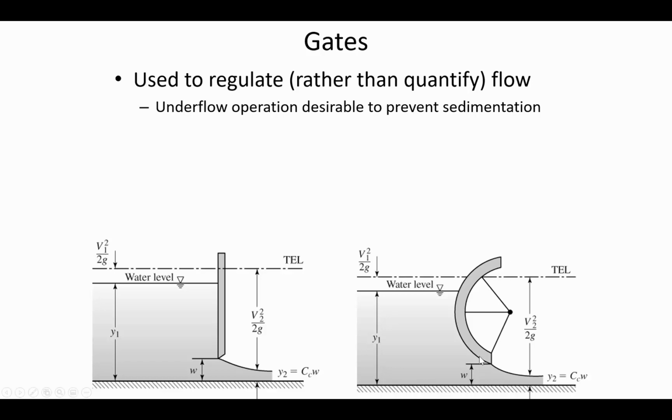So here's that cross-sectional view of a radial gate that I was mentioning, and what you can probably visualize is that the hydrostatic forces that are acting on this radial gate point inwards towards the center of rotation. And so since the direction of the force is towards this rotation point, that means that there isn't going to be any moment distance or any kind of force that prevents it from being lifted other than the weight of the gate itself. There isn't that same frame pressing up against the gate pressing against the frame and additional friction issue.